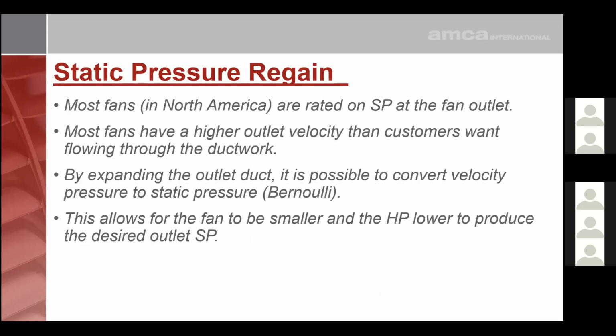We touched earlier on something called static pressure regain. Essentially, a fan will have a fairly high velocity at the fan outlet and it has a high velocity pressure, but the pressure required to do work through the system is static pressure.